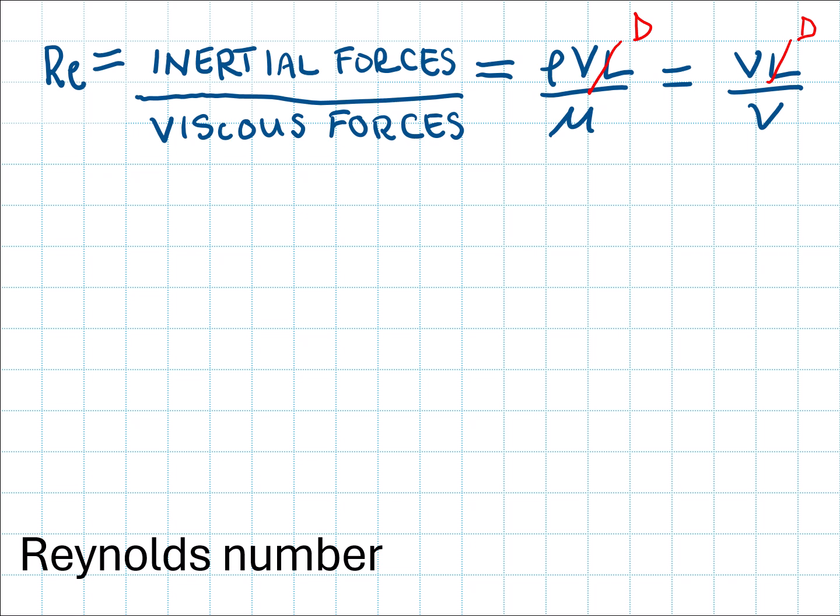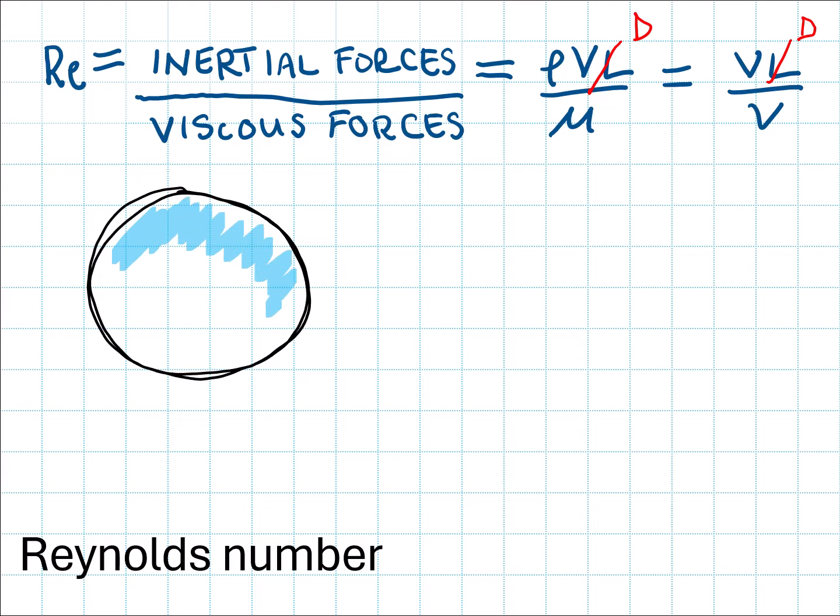What do I mean when I say this? Well, let's say that I have a circular pipe cross-section like this. And then my flow area is the internal pipe cross-section like this. And these black lines are my physical boundaries, the pipe wall. So my characteristic length scale is going to be the size of fluid flow within these physical boundaries that is going to constrain the size of turbulent eddies that can develop.